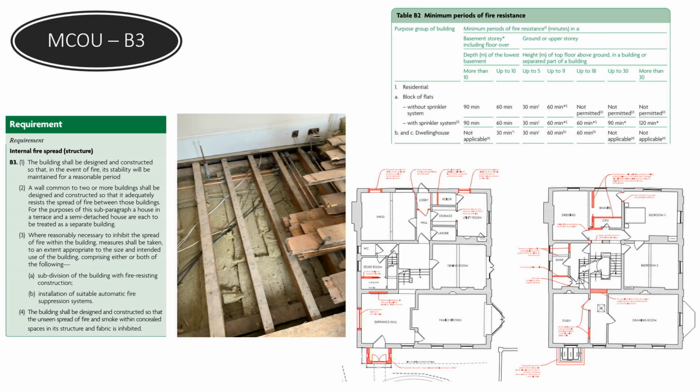And what we actually did in this instance is provide 3 solutions, well, the designer did. To the rear of the building, the listed officer wasn't particularly interested because it was completely shattered in terms of dilapidations and all the rest of it. So we overboarded the existing ceiling, relatively simple, gypsum white plasterboard, and achieved the necessary fire resistance.